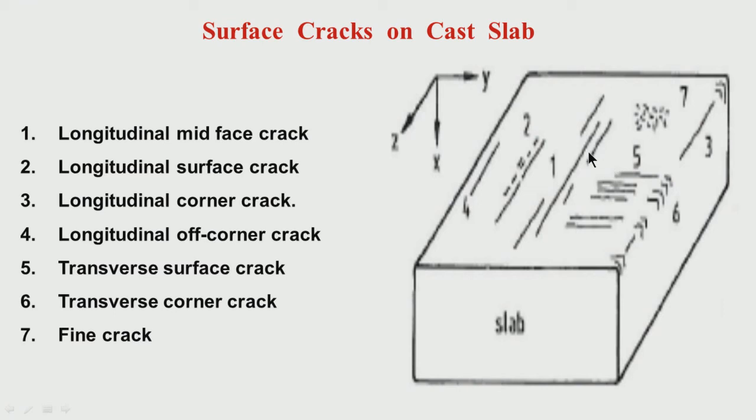Either in the mold, there will be initial stage of solidification, or as I mentioned, for certain chemistry you have very coarse structure. Because of the coarse structure, the cast grains are coarse, the grain boundary areas are less. So, at temperature of 600 and 700, that means when you are cooling it, there is a possibility, if you cannot avoid that particular area, if you pass that temperature area in a relatively long time, for the shell to be in that brittle temperature zone of 600 to 700, you may generate cracks because of the formation of nitrides. So, coarse grain is the culprit there.